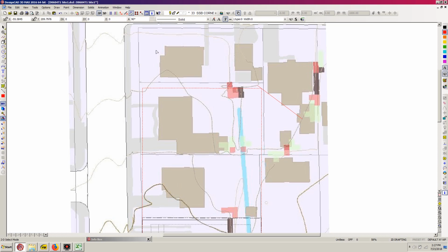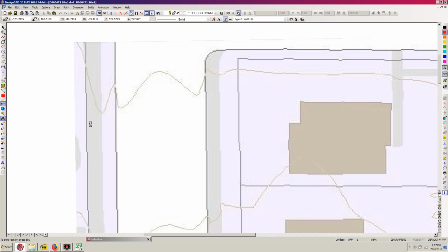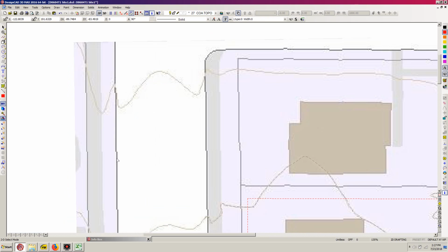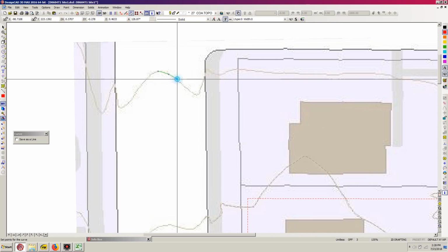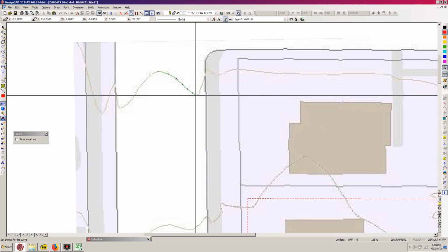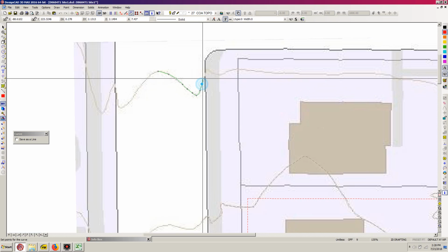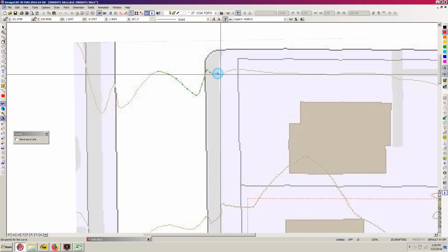And to do that, I'm going to zoom up here a bit and go to layers, get my right layer, COA topo 27, OK, and hit C for curve, and just do a quick and dirty topo line here. Just needed another one. Just clicking over this line, doing an overlay. Hit escape. Oops. Get going too fast sometimes, but hey, it happens.